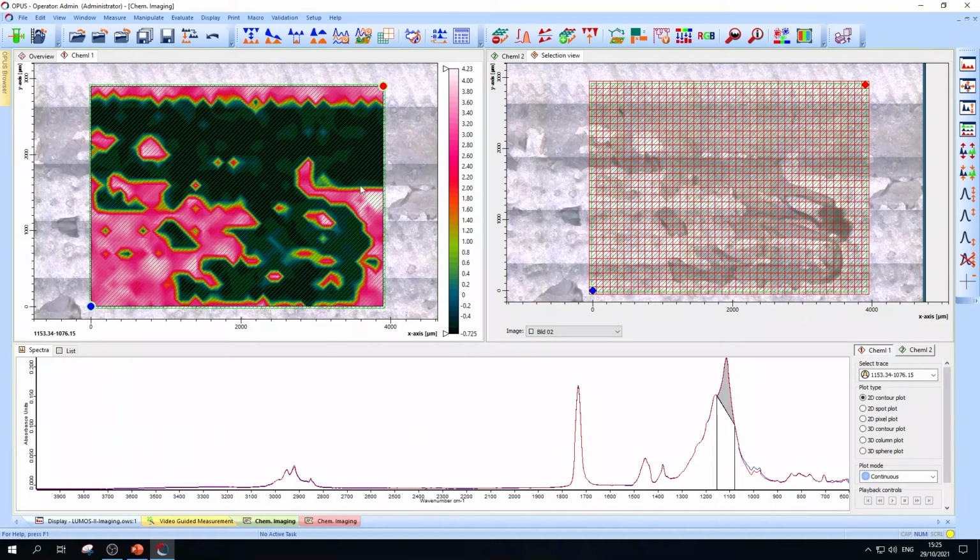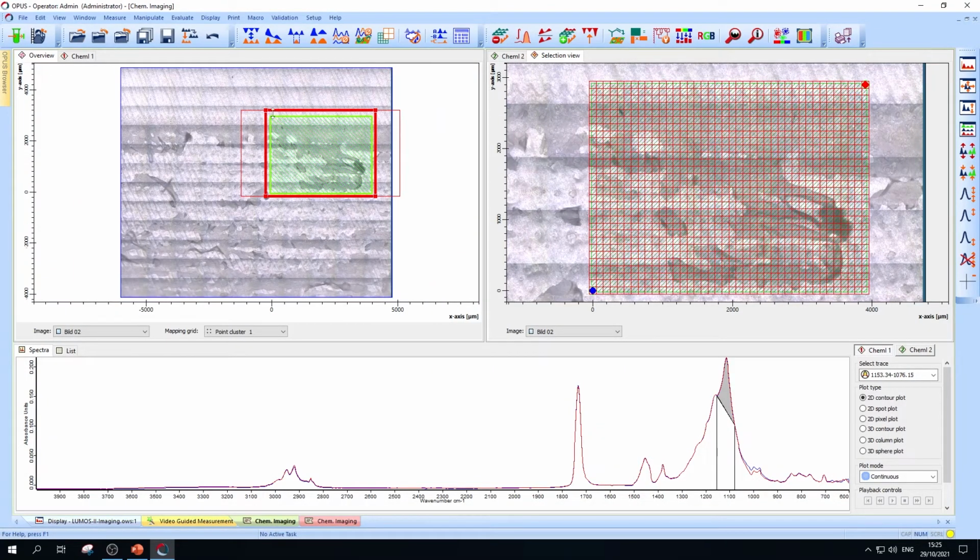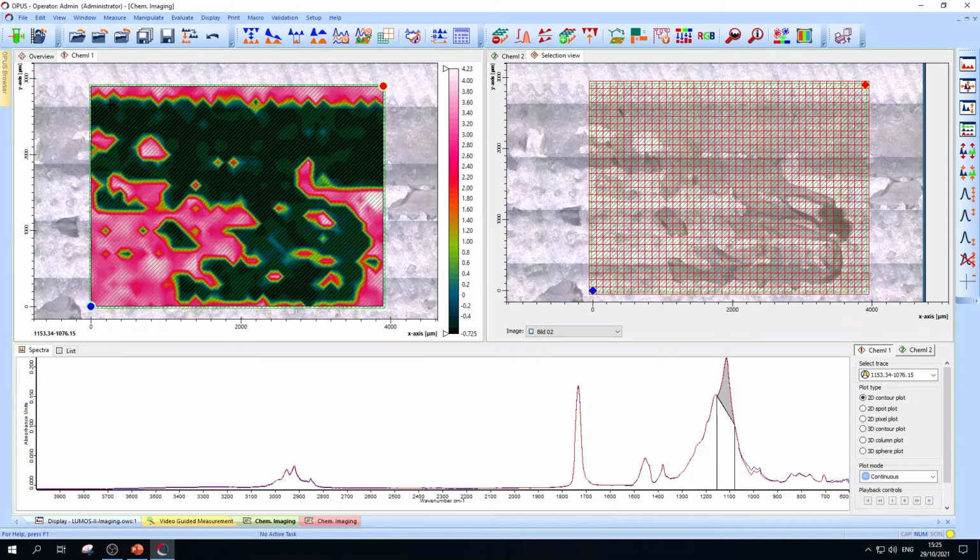So what you see here is the measurement area which has been applied. So these are 40 by 30 ATR measurement spots. That means each red square indicates one ATR measurement spot and therefore also one IR spectrum. So this measurement area has been applied over the interface between, on the whitish ground, the foil's inner face, and in more grayish colors here, the cold seal adhesive. So if we have seen here on the magnified view on the top here and also on positions there, this is the foil's inner face, and on the grayish here, this is the cold seal adhesive.